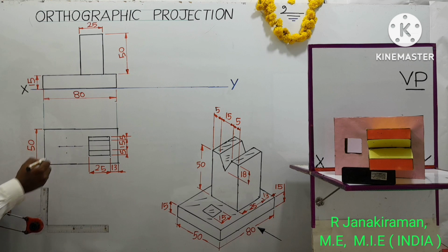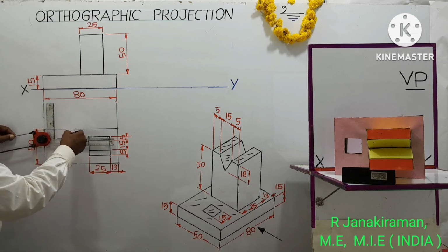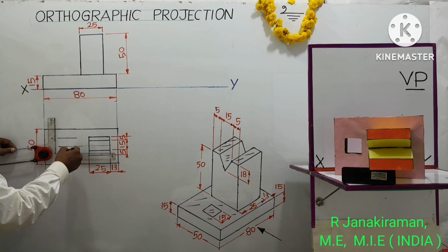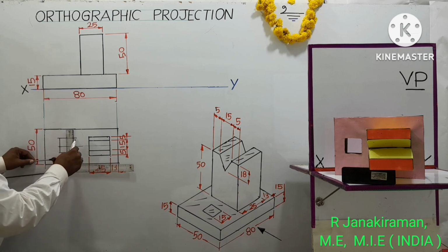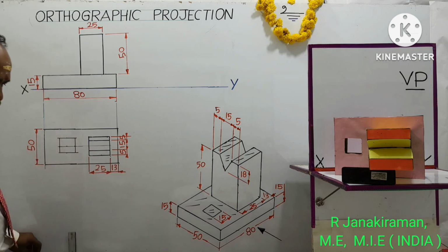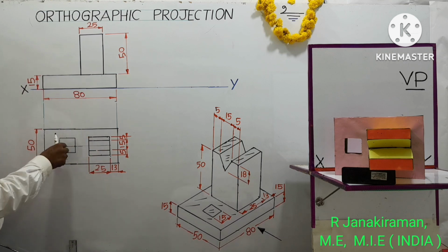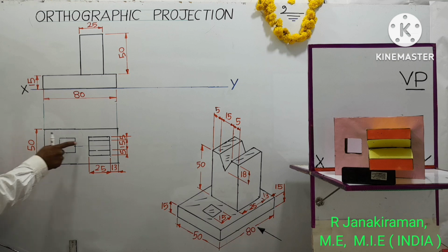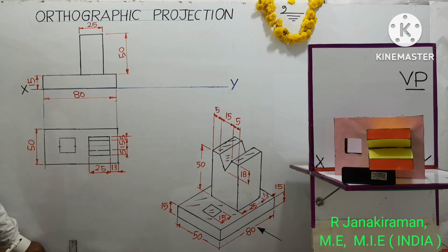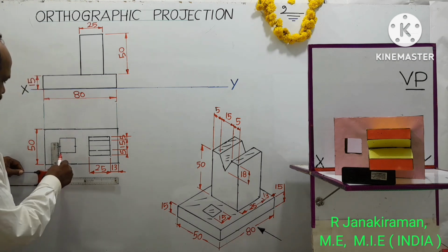Okay, so draw a square hole; you will get a size of 15 mm automatically by drawing horizontal lines passing through those points and vertical lines passing through those marked points. So you will get a square hole. The remaining segment you can erase, and later you can remove that roughly drawn line. This is how the square of size 15 mm is obtained.